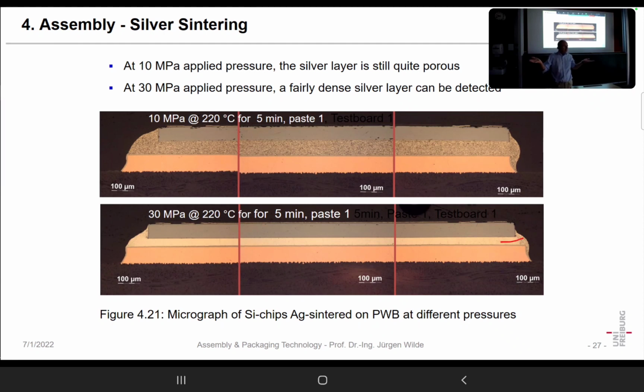When it is detached, the thermal resistance increases. When the thermal resistance increases, temperature increases. When temperature is increased, crack propagation is faster, and very soon, when that has started, it's the end of the chip. Normally it doesn't fall off, but it will just blow up or overheat and fail in that way.